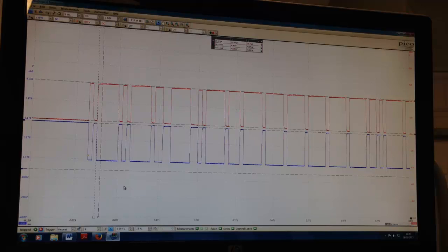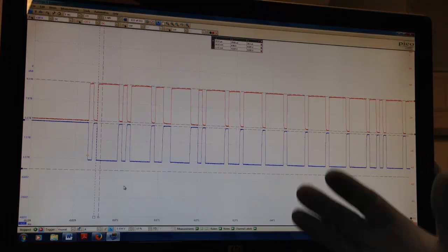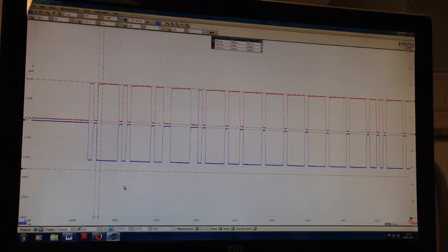So all I'm going to do now is go back to the car and do some wiggling, and I'm going to plug that connector in firstly and see with it plugged in, do we still have a good clear CAN signal? And then once we've plugged it in, we're going to see if the function on the car is okay, and if the function of the car is not okay, we'll do a little wiggle test while we're looking at the CAN and see if we can see what's going on.